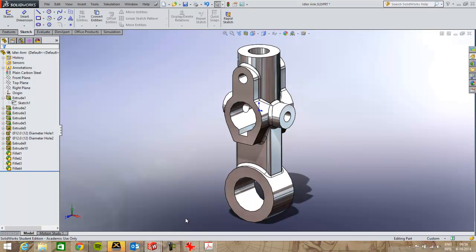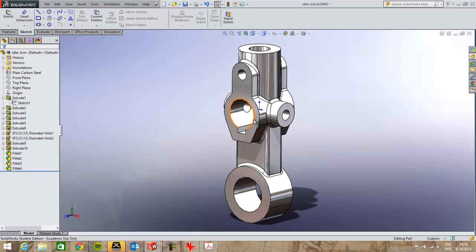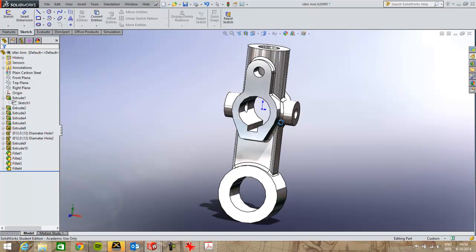So I'm going to start modeling this and show you that it's quite easy as long as you're following some set of rules, and that's particularly that you put the origin there where the most features are coming together. It's at the blue point over here, that's where I put the origin of the part. For the rest, it's really important to model as symmetrically as possible, so you do all the work that you have to do only once, which makes it easy. And then I'll start modeling.